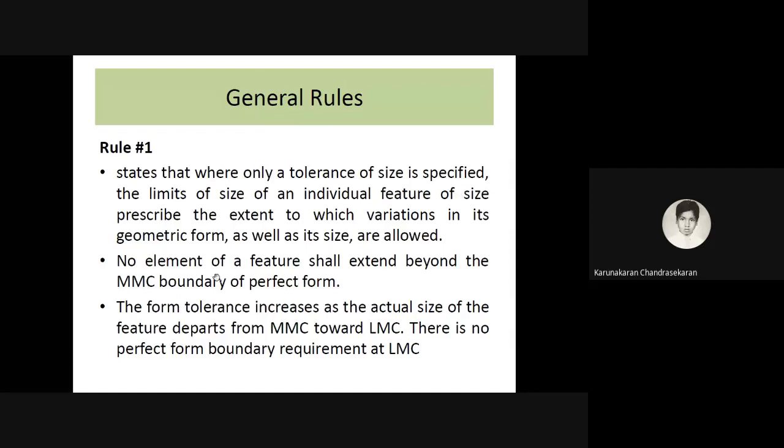And no element of the feature shall go beyond the maximum material condition boundary of perfect form. This is another very important point to be considered. The form tolerance increases as the actual size of the feature departs from MMC towards LMC. So there is no perfect form boundary requirement in the case of LMC.